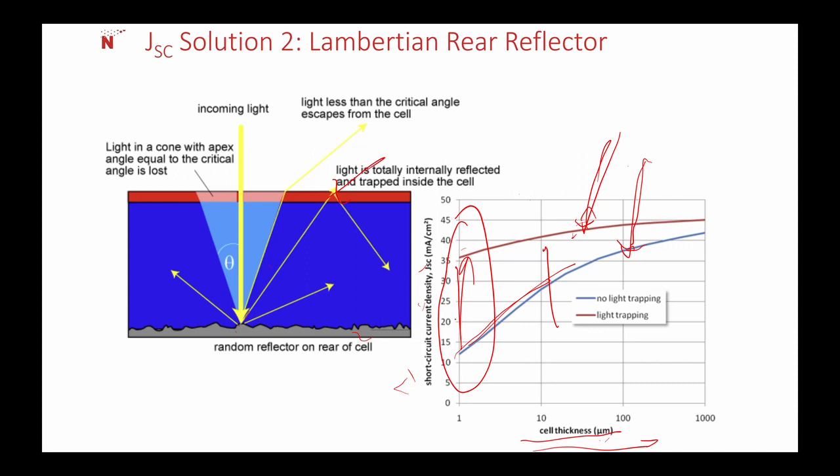The larger increment is in this region, because we have increased the effective length. If our cell thickness is say 5 micrometer, which is in this region, and 10 micrometer, those are two cells. We are increasing the effective length in this region as well, and in this region it was already absorbing more light because of the greater thickness. So the maximum current could go only this much.